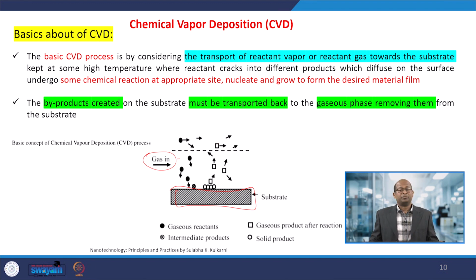Some reactions take place over the surface, and with film formations or nanoparticle formations, some intermediate or gaseous byproducts are formed. These are the byproducts, and this is any intermediate product that may form, and this is the film formation actually. So when the gas molecules decompose, elemental carbon or graphene or CNT type of material forms or deposits as a nanofilm over the substrates.